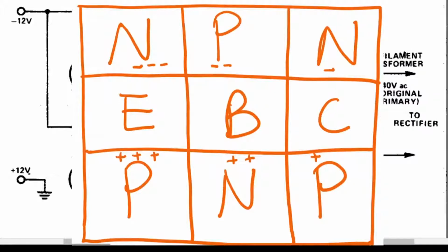In the other video I had talked about this, saying the polarity that is seen is the odd one out. So P is the odd one out in NPN. So the odd one is the base. For PNP transistors, the N is the odd one out, so the odd one is the base, always. So for NPN transistors, the emitter is the most negative.